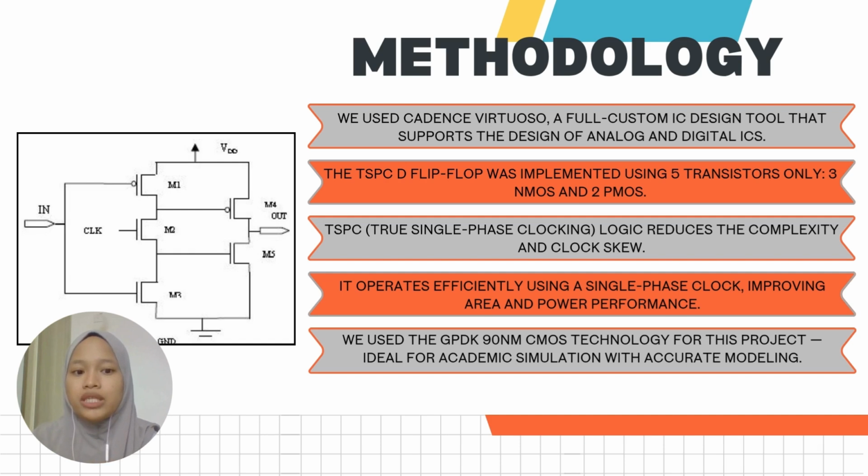This compact structure reduces not only power consumption, but also the propagation delay and chip area, which are all crucial in modern VLSI circuits. The TSPC flip-flop is designed to avoid clock skew issues and is well suited for high performance and low power applications.